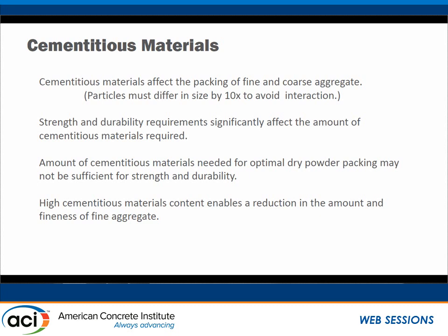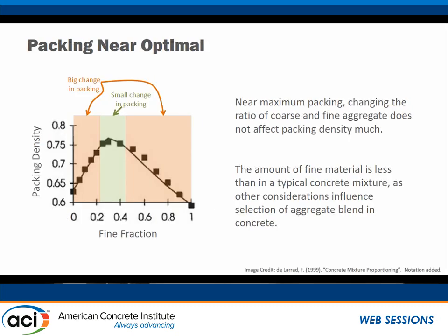And so, generally speaking, as we go to higher cementitious materials content, we can reduce the amount of fine aggregate and still have a good rheology to that concrete mixture. Another caveat to make about packing is that the packing near the optimal often doesn't vary very much.